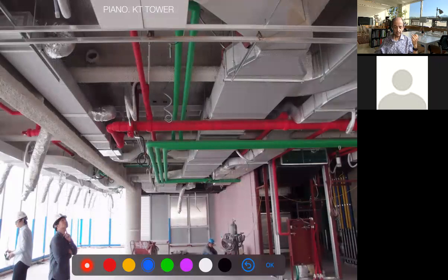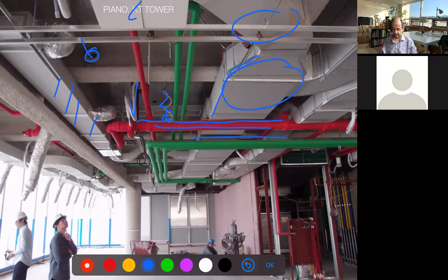As an example, this is Katy Tower, the example we bring very often. This light changes, and you see in a very well-planned tower how much space is taken by the ducts. See how many beams have openings to have ducts in, and as we said, you have the air on the top in general, then electricity, and then pipes just in the lower part. This is the most general way of doing things. But you see that there is a connection. So here the space is so tight that mechanical, plumbing, and the structural engineers have to really check and cross-check the working drawings so there will not be any disaster.